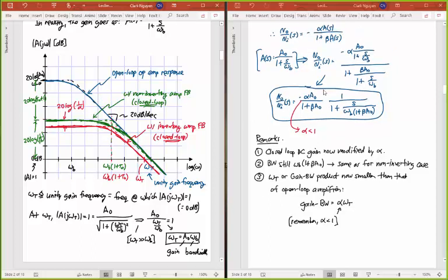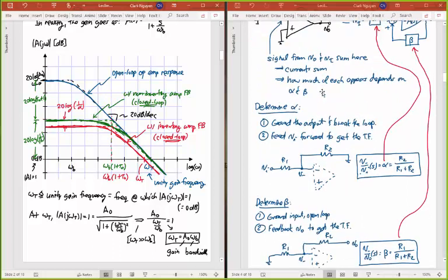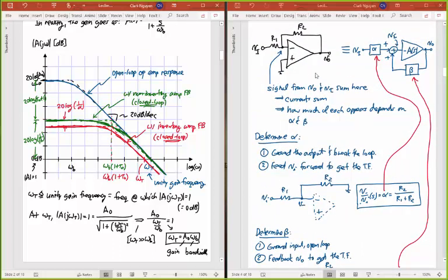But in the end, when you make an inverting amplifier like this, what you're really creating is an amplifier that really wants to amplify current to voltage. So the input it really wants is a current into the minus terminal. And in this case, we're giving it that current by sticking a resistor here, and VI is being divided by that resistor. We have to create that current through this resistor. If we just had a current going straight in, this amplifier would love that.